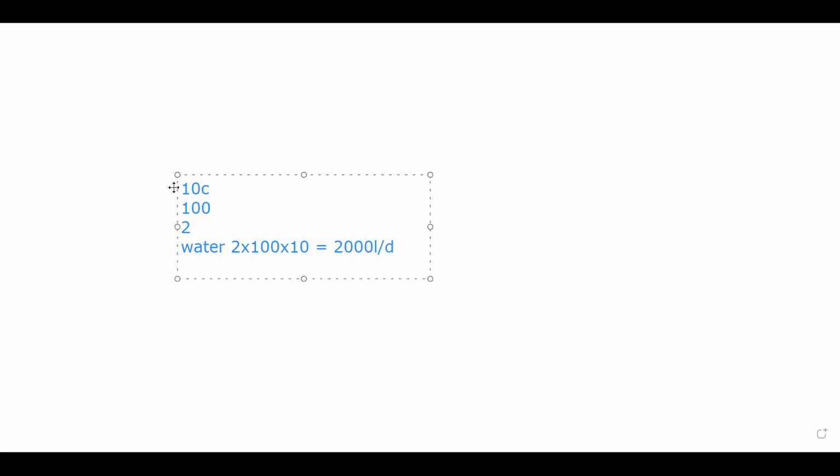If we now convert it by dividing it by 24 by 60 by 60, we'll come up with 0.023. So that means for those 25 houses now, it will be 0.023 times 25. So that becomes the water demand that I will put in node 6.